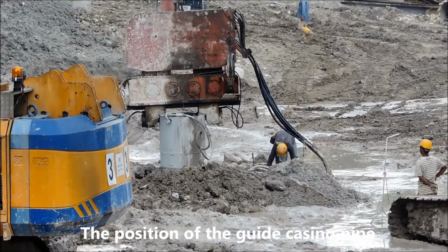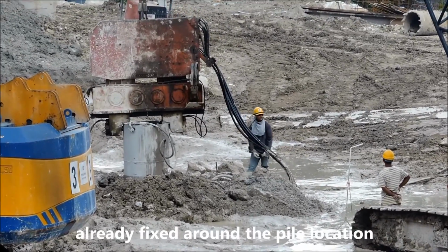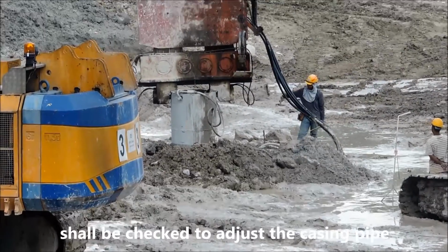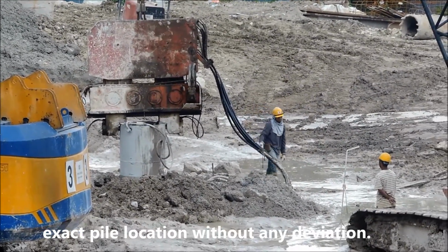The position of the guide casing pipe with reference to the pile reference point already fixed around the pile location shall be checked to adjust the casing pipe to ensure proceeding of drilling at exact pile location without any deviation.